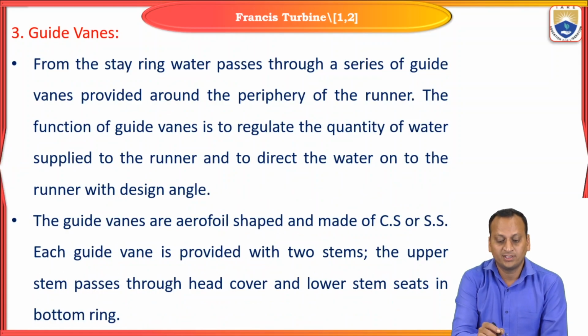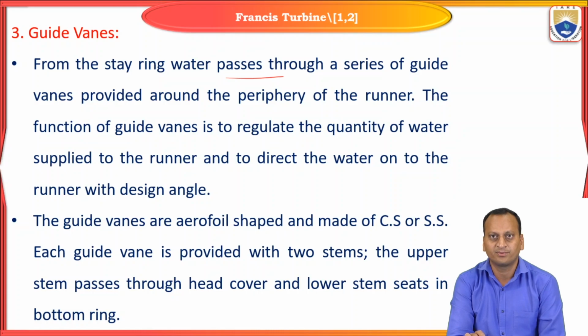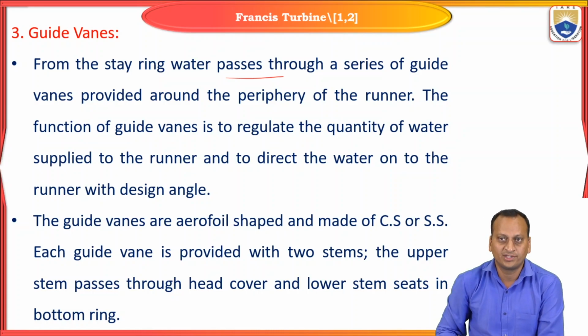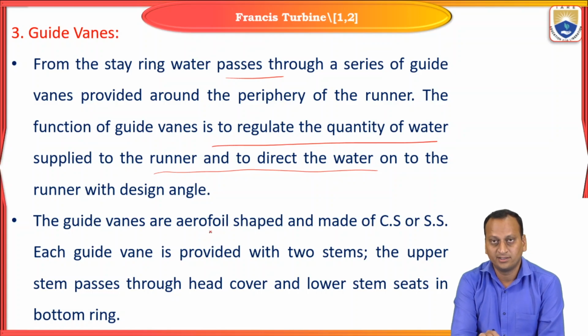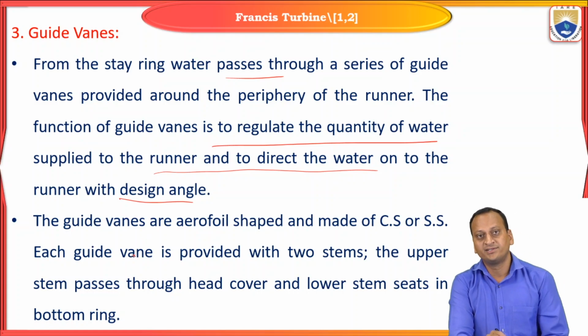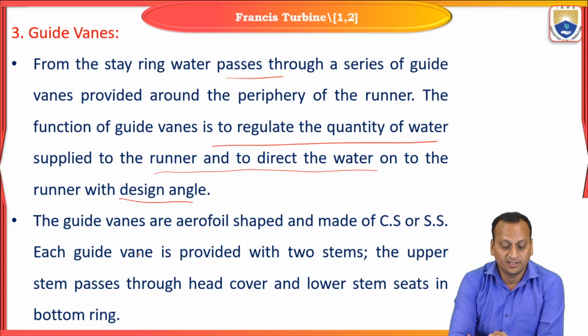The guide vanes. From the stay vanes, the water passes through a series of guide vanes provided around the periphery of the runner. The function of the guide vanes is to regulate the quantity of water supplied to the runner and to direct it onto the runner blades at a designed angle. The angle of attack of water will be decided by the guide vanes.